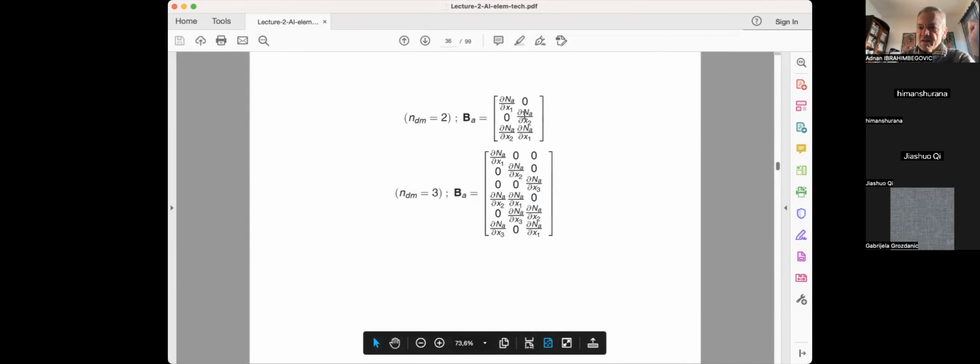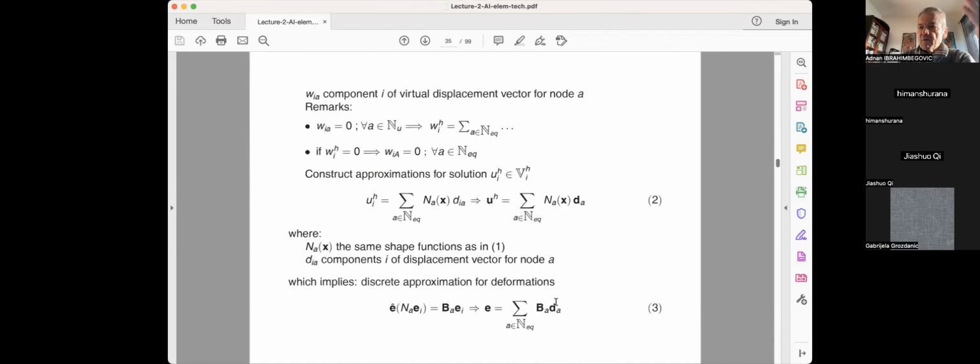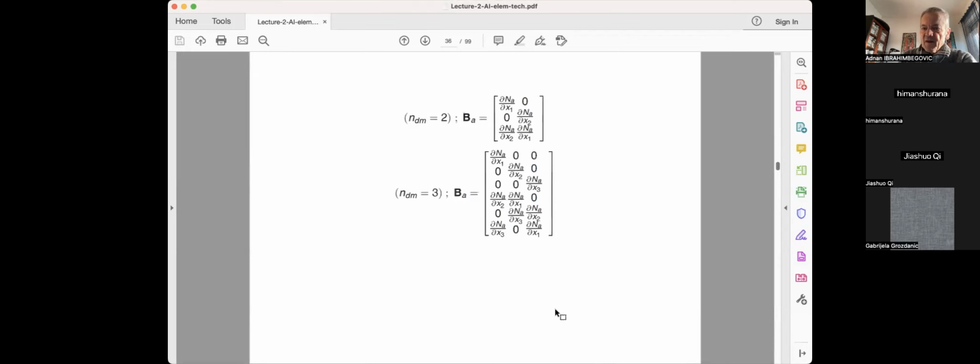And for this case, this will be d1, dx1. I just have a d and a dx1 because d1 will be in this vector here. So it goes also here, d and a dx2, because d2 will be in that vector. And here will be d2, dx1, d1, dx2. Basically, I have it here in the shear part. If I have a 3D version, it will be extended. I'll have the third dilatation and 2 other shear deformations to have this matrix B.